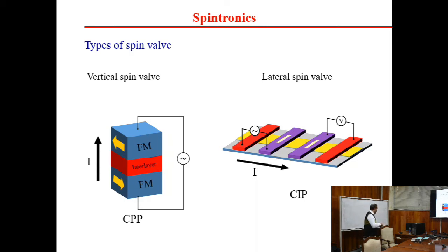In the case of a 4-probe measurement, if I talk about the FET, what we do is apply the current here and we measure the voltage. It means you are measuring the voltage within the channel. That is known as local measurement. The current is flowing and we are measuring the potential difference between the two terminals.